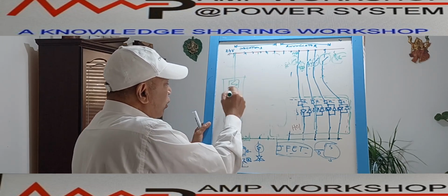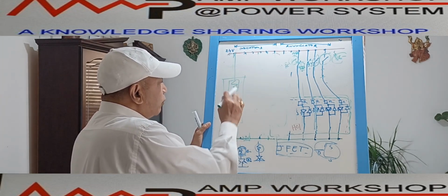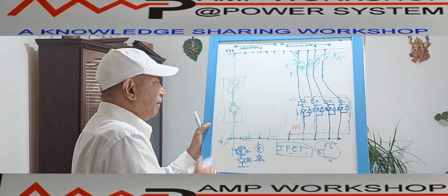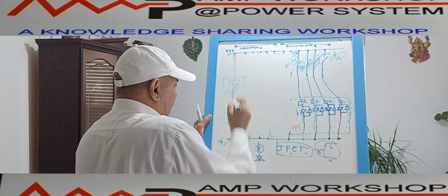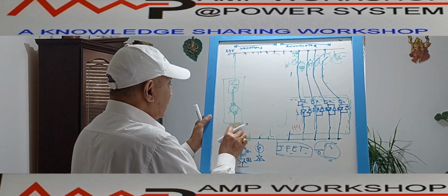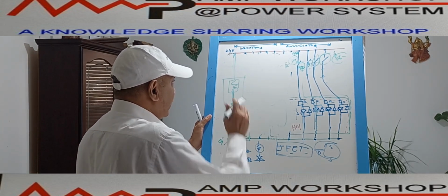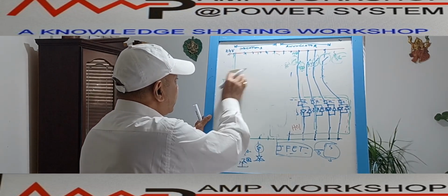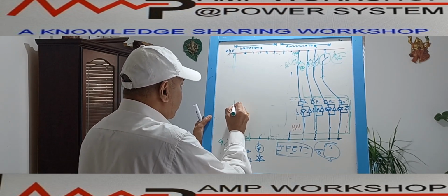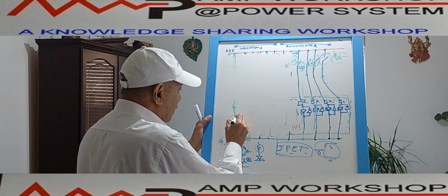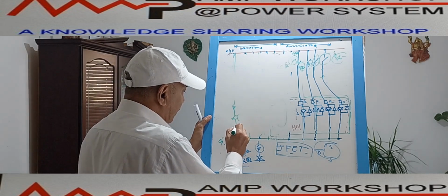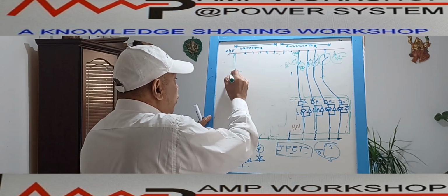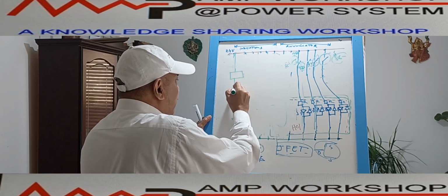This is one of the windows, indicated by this lamp, and this is your actuating parameter, connected over here. I can draw it slightly downward, then it will be easy to make out. So this is your ballast resistor and this is your indication lamp, connected to the negative bus. And we put one auxiliary relay over here with a push button.